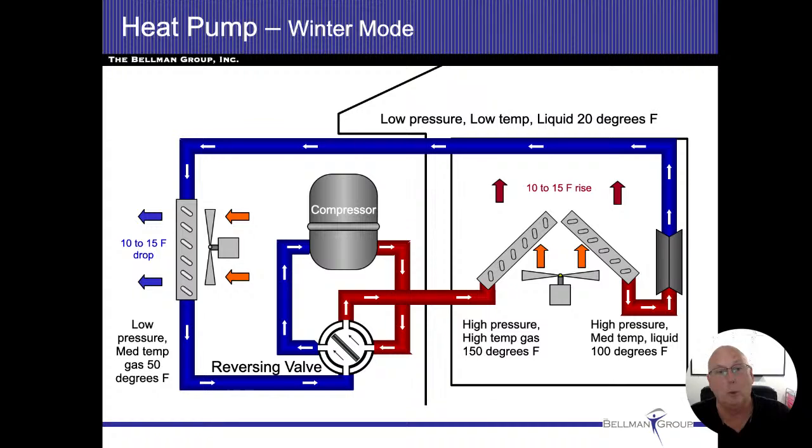And now that cold liquid goes outside, colder than what it is outside. Now, even if it's 40 degrees or 50 degrees, if my refrigerant's 20, then I'm still warmer outside. I could still absorb heat into my refrigerant on the outside. Cause it to boil, so now my outdoor coil, which used to be my condensing cabinet, is now my evaporator cabinet, because now I'm causing it to boil, change back to a gas, gas comes to the compressor, and so forth. So a heat pump, or I should say an air conditioning system, is technically a heat pump, all right?